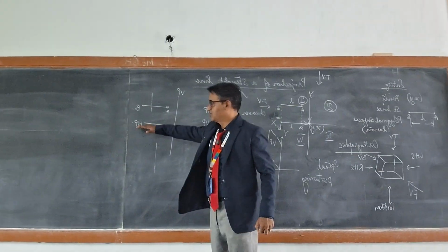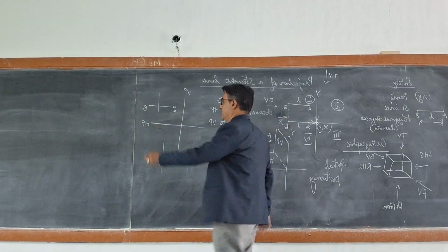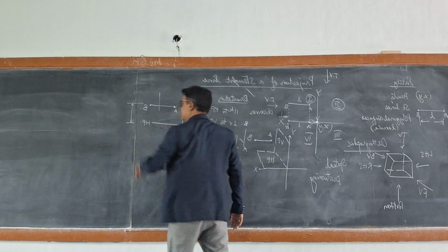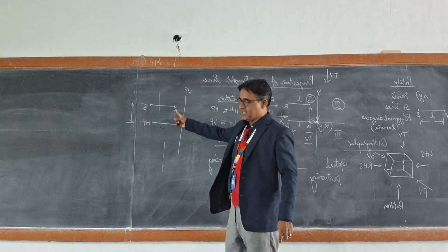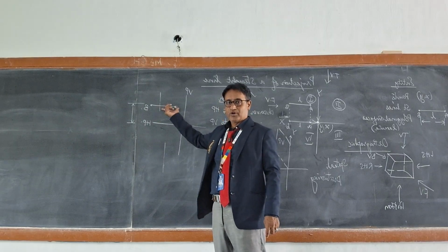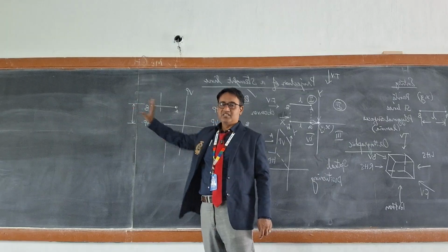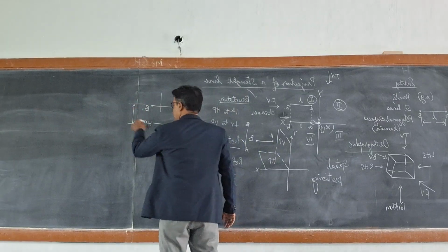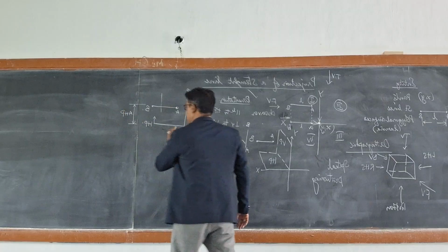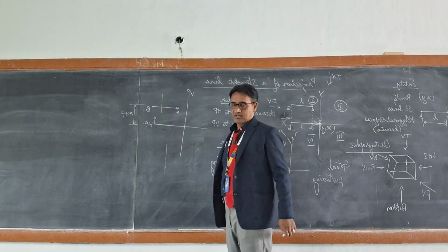With reference to this horizontal plane, you have the distance of this point A or point B, because it is parallel to HP, which is referenced by means of a particular distance. And this distance, I call it, say, this is above HP. See, this is HP, the distance is above HP because the object is placed in the first quadrant.